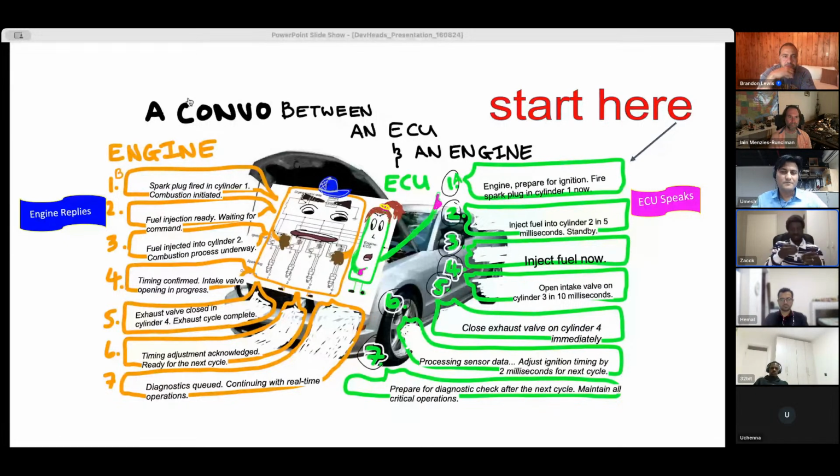All of these things need to happen in a sequence, and they always need to happen in that sequence as many times as possible. These are the situations where you would need an RTOS. You have timing constraints. It's not just simple delays, but time problems that depend on other time problems, and they need to happen in a certain order. Otherwise, you have what is described as catastrophic failure. We can go to the next one.